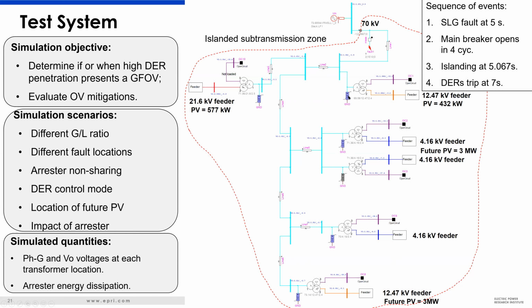And here is a look at the speed of the motors. The objective here is to show you that after islanding, the frequency of the network is characterized by the speed of motors. So you can see that the frequency basically declines gradually and slowly, and that means that the DER frequency protection may respond slowly. So our study suggested that the fastest acting protection was the transformer 59P. And so for both PVs, the overvoltage protection and the frequency protection did not act fast enough.